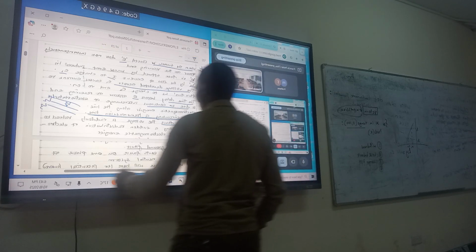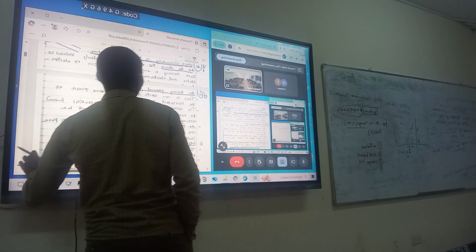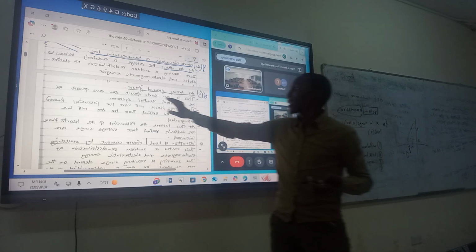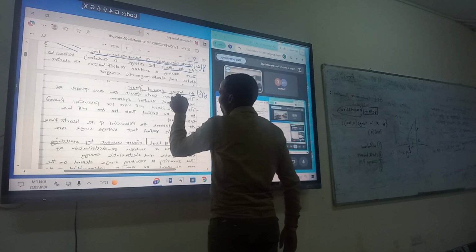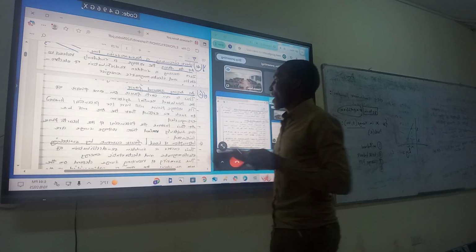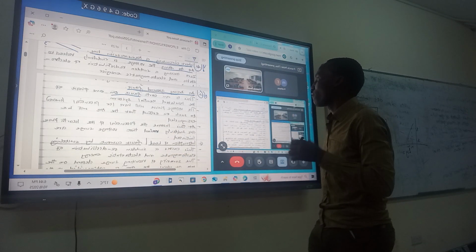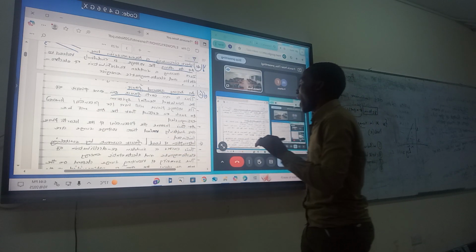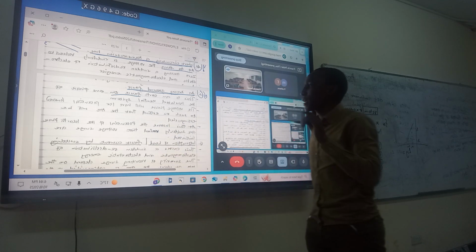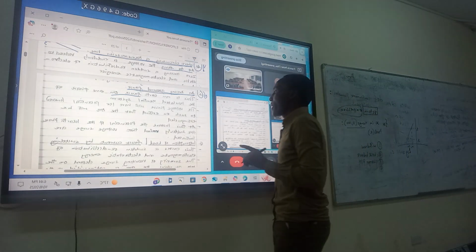Another point, number 5, we can say that an arcing, we learned arcing. What is arcing? By the way, in protection we learned that. So an arcing ground fault is an earth fault on one phase of the insulated neutral system, and therefore the voltage of the phase will have its potential lowered to such an extent that the arc will be extinguished.